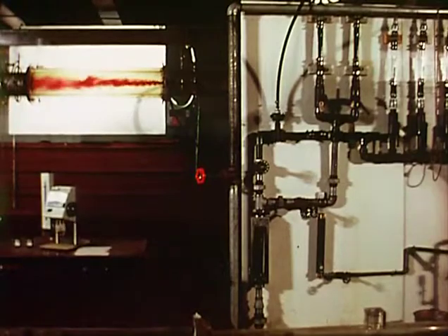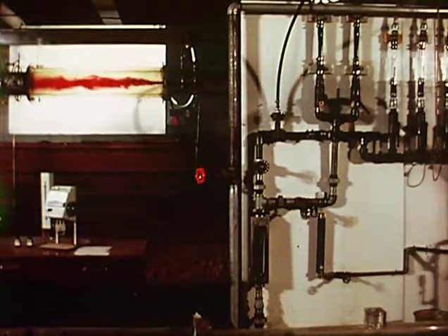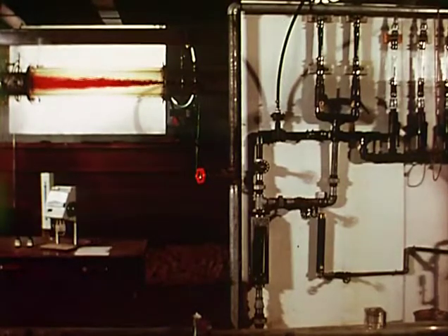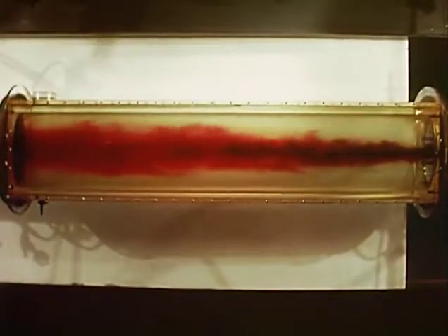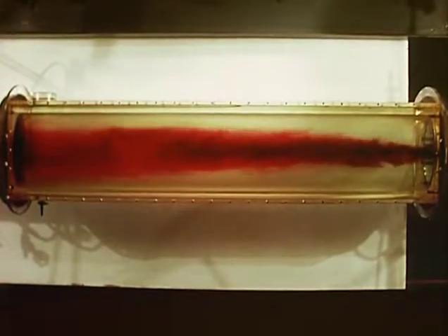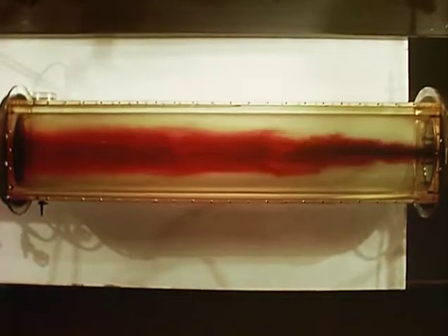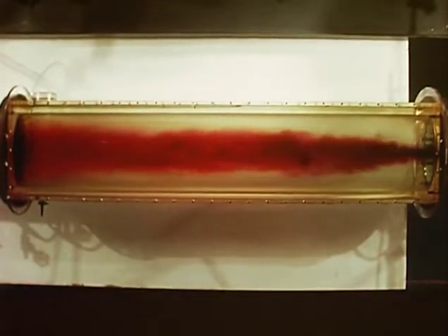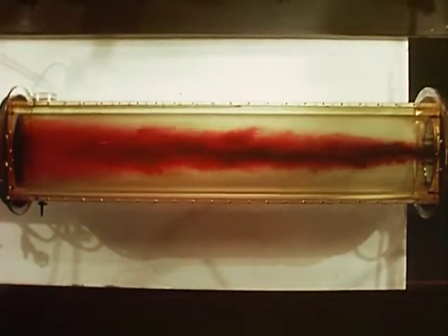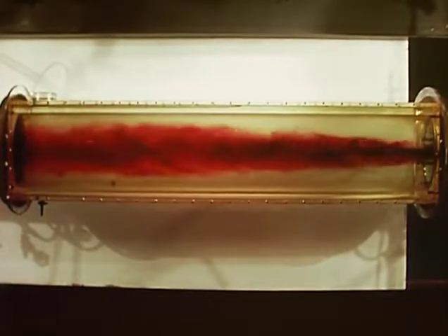The following scenes are shown at 3/8 normal speed and show dispersion within the first 6 diameters of injection. You are looking horizontally at the flow. In this and the following scenes, the pipe velocity is 5 feet per second and the injector extends 3/4 of an inch into the pipe. A single injector is located on the horizontal diameter of the pipe.